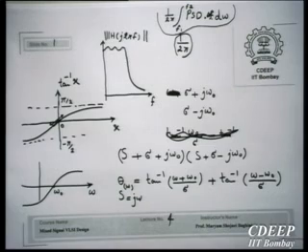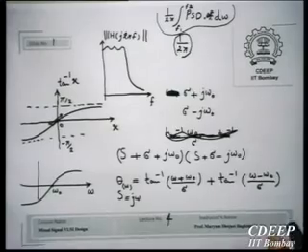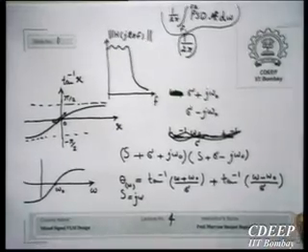But we implement many band pass filters in the form of high pass plus low pass. Therefore, this is how a high pass filter doesn't show a very high noise at the output. You simulate, and then that will help you to understand what is happening and why the power spectral density of noise is actually not increasing with frequency.